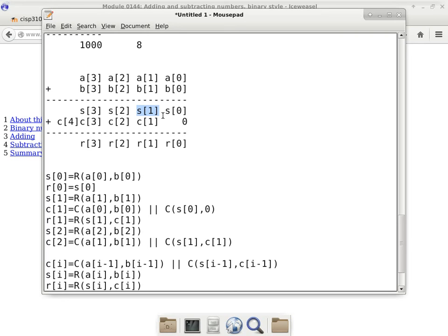If S1 is a 0, then it doesn't even matter what C1 is, the addition of those two cannot give you another carry. So that means when you're dealing with the expression of CI, we know for sure that only up to one of the two sides can be a 1. They cannot both be 1s. So that's a very good question, and I hope the answer is sufficient. Basically to prove that it's not possible.